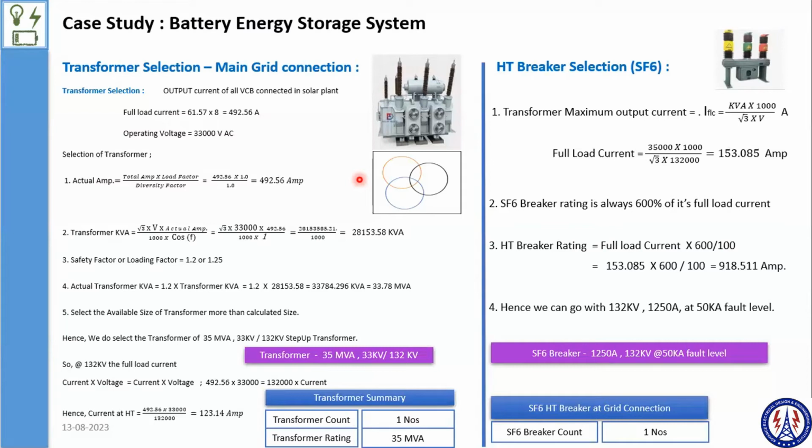The plant should operate with its functionality because it's AC coupled. But if there is a problem with the PV plant, why don't we shut it down? No, I'm saying the battery plant is facing some problems, and you shut it down for the battery. And your entire factory is under maintenance. Let's say the critical scenario. It won't happen, but the system should have the ability to sustain within that duration. Otherwise, you need to shut down each inverter.